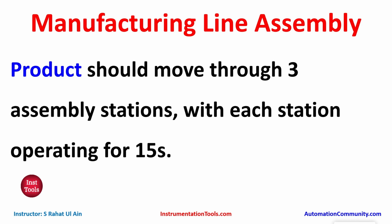We will also use some memory bits for this operation. With that also, we will be using a timer like TP, that is pulse timer. So let's move to EcoStruxure Machine Expert, where we will draw a ladder diagram for manufacturing line assembly.